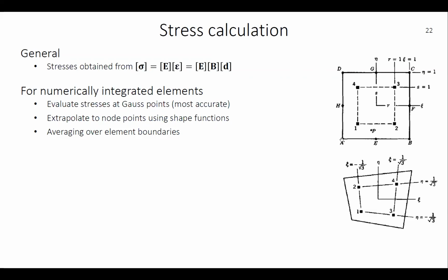So the displacement at this intersecting node will be the same, but the evaluated stresses may not be the same coming from different elements. So you extrapolate the stresses to nodal point A, and then correspondingly from the adjacent element. And they may have different values, most likely.